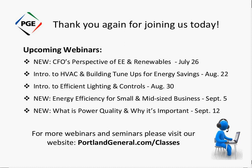Now, demand is just kW. It's the highest number of watts that you're using during a half-hour period. The utility needs to know that because it has to build a system, transformers and wires, et cetera, that meet your peak demand. So it's a very helpful number for what is the load that we have to build to support.